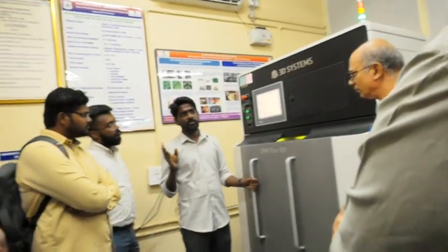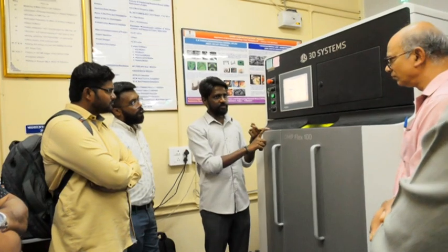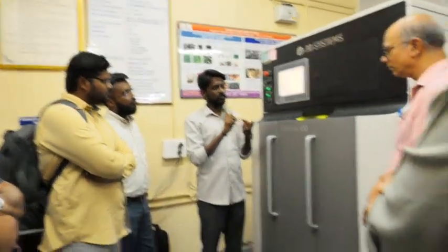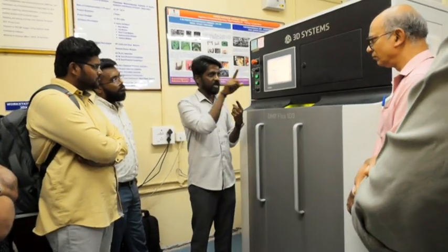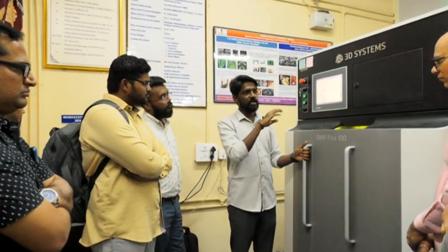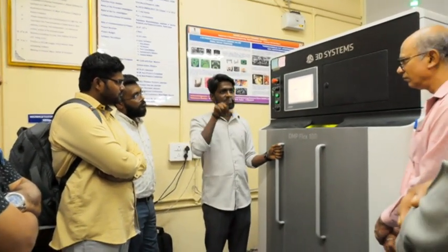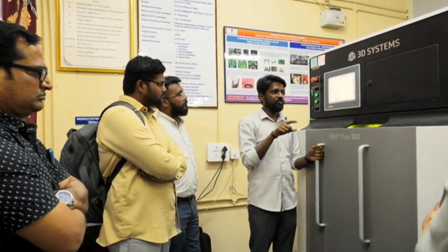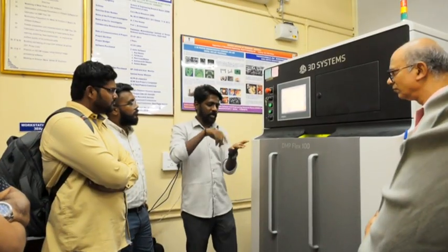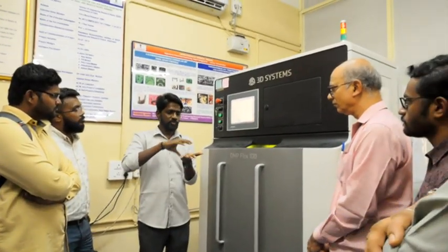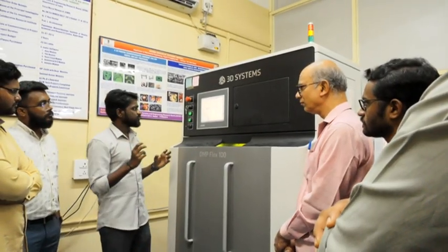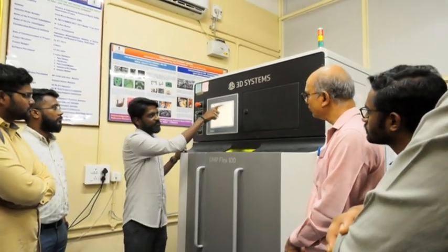In the 3D software we can change the hatch spacing and hatch pattern. There are different patterns, like rectangle pattern, chessboard pattern, rectangle stripes, followed by hexagon in and out. We are following the hexagon in and out strategy. Why? Because it takes more space and more time to get a more precise part. And this is the basic user interface.